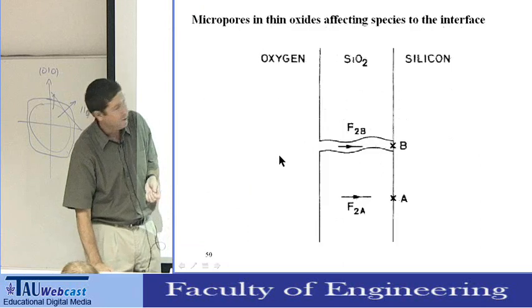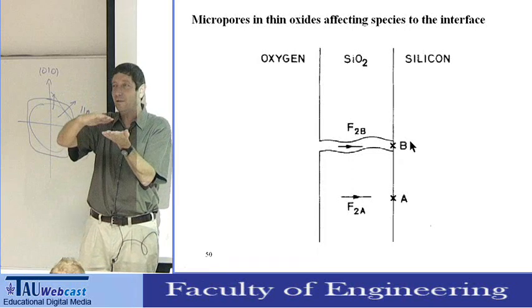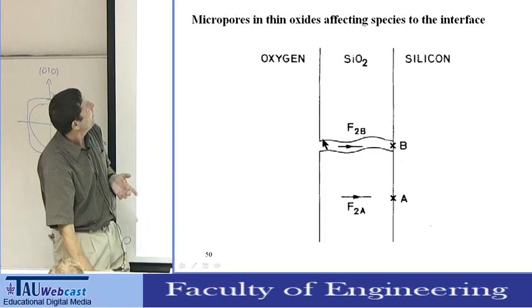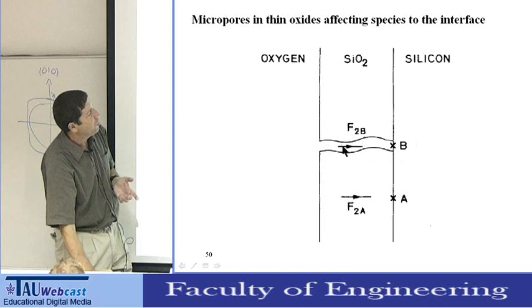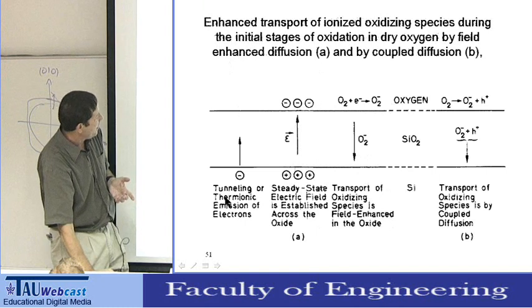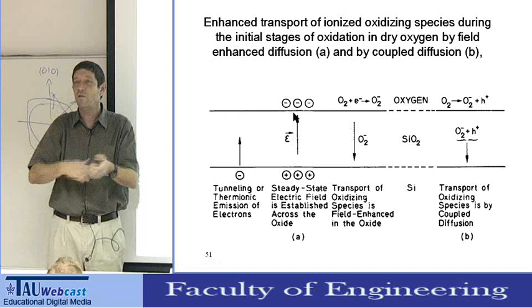For example, for very, very thin oxide, maybe the oxide is not complete. So you have some roughness, or nanopores through the oxide, so you have to include them. The other models are tunneling effects. For very, very thin oxide, you can have some charge effect and tunneling effect.